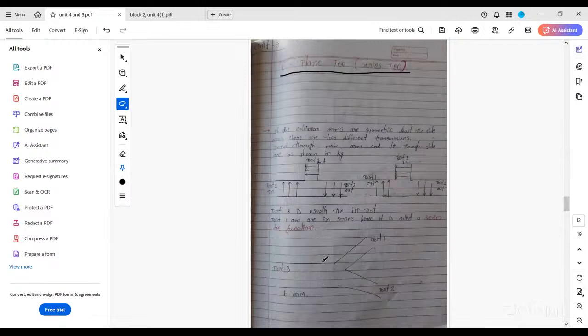In this E-plane T, we are using 3 ports. Input port is represented with port 1. Here, port 2 is represented as output port. Then this port 3 works as an output port only.